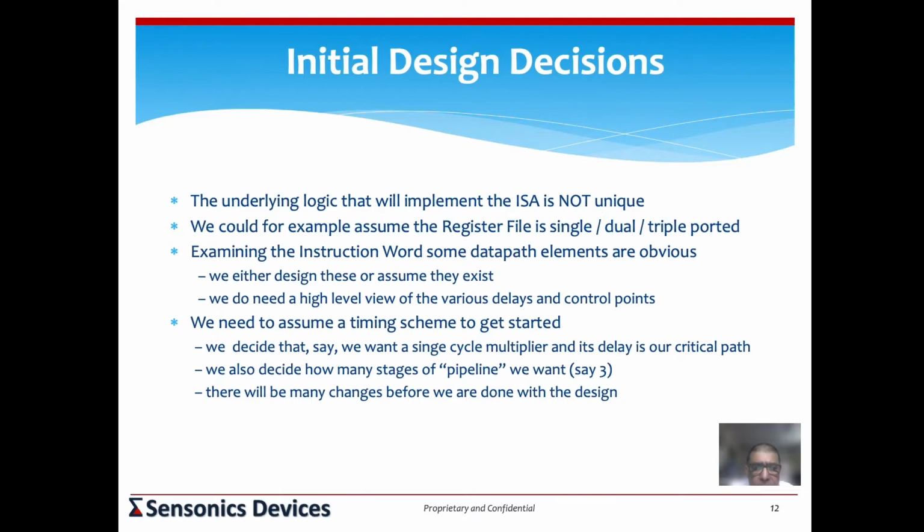No, probably not. But you need to have some sort of a sense, in the sense that when you look at a multiplier's critical path, you know exactly how many muxes and how many full adders are in that path. And accordingly, you obtain an estimate. And then you look at an ALU and you find out how much you get, and you find it turns out the ALU is maybe only 75% of the delay of a multiplier. So it means that you could add something more in the ALU's path.